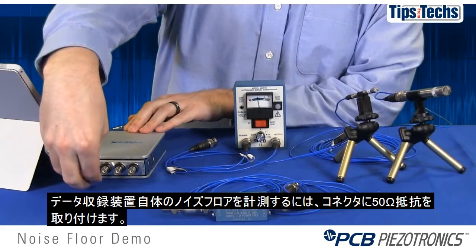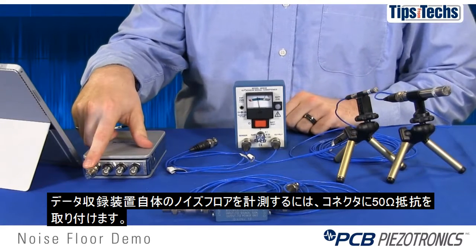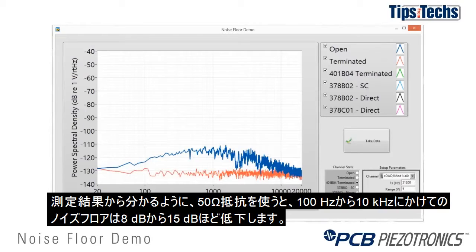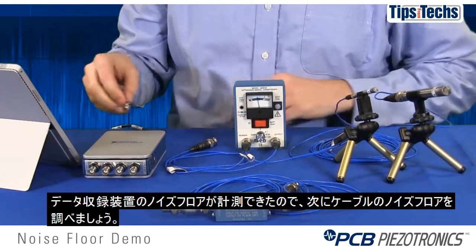If you really want a noise floor measurement of the data acquisition system, you should terminate the connector with a 50 ohm terminator, as you see here. And as you can see by the result, the 50 ohm terminator lowers the noise floor from about 100 hertz up to 10 kilohertz by anywhere from 8 to 15 dB. And we have a nice flat noise floor now. So now we've defined the noise floor of the data acquisition system.